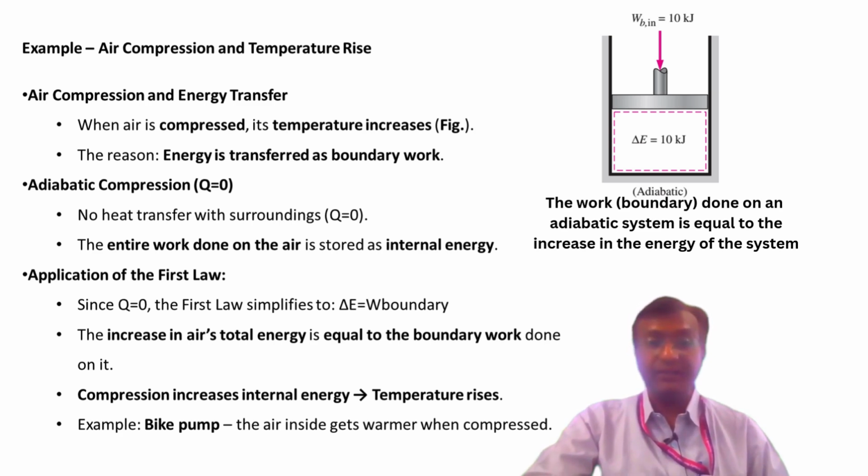The speed at which the gas is compressed is important because a fast compression won't allow much heat to escape, whereas a slow compression, however, will allow the heat to dissipate and the final temperature after the compression will be lower. Therefore, by compressing the air, we are not creating energy, but rather converting mechanical energy into thermal energy, resulting in a temperature increase. This provides a practical and relatable example of the first law of thermodynamics in action.